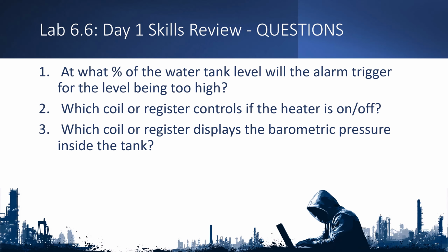I also mentioned, well, which coil or register displays the barometric pressure inside the tank? And so can we read those registers and determine, of course, comparing those values to the HMI, which is the appropriate coil or register? Even just knowing at this point, is it going to be a coil or a register?